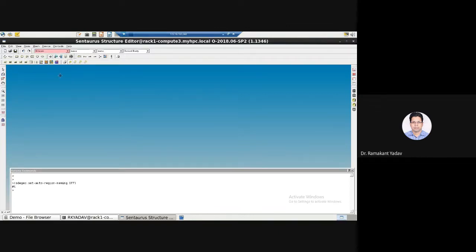Next, we will be designing devices of different sizes, so you have to give the different dimensions of the device. To check the dimension of the device, select this. You can go to draw exact coordinates, and select it from here or on the right side. This is the shortcut icon for exact coordinates. Whenever you are drawing, suppose, a rectangle, it displays the coordinates of this rectangular window.